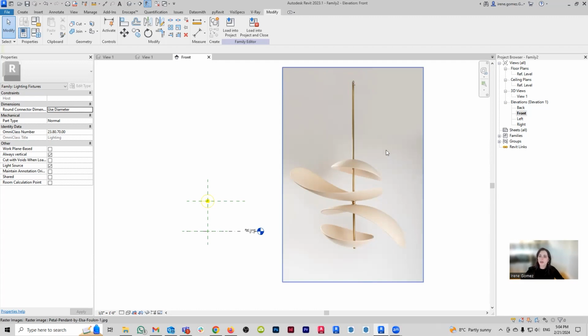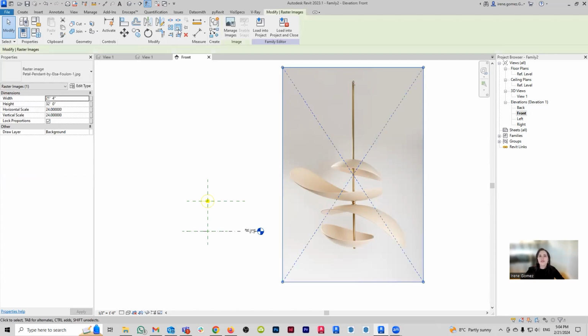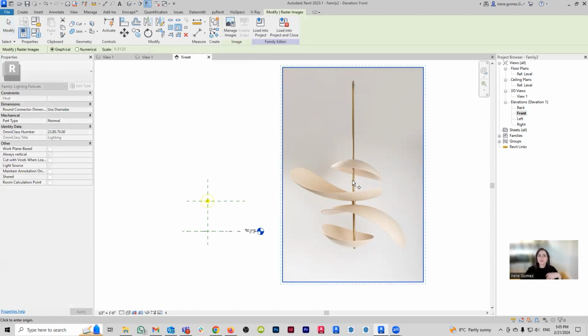resize or scale an image, you're going to select the image and find the scaling command here, quick key RE. So I'm going to go RE. And when you're scaling, there are two ways that you can do it, graphical or numerical. Numerical means order of magnitude. So you basically make something 3 times bigger, half the size, 20% of whatever it was. You're just saying whatever it is, it's going to be less or more by this percentage.